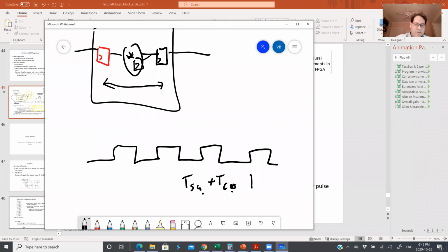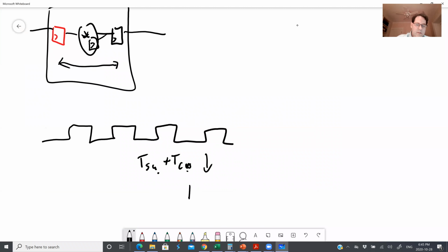All right, so that gets smaller. But the hold time does get bigger. For FPGAs, it's not a bad trade-off. Also, the register area, because you're only building one latch instead of two, gets smaller. So as long as you don't have to build too many pulse generators, you can amortize those using the technique we just talked about, then you can save area. And FPGAs have a lot of registers, so it's more important to save area on them than it would be in a lot of types of devices.